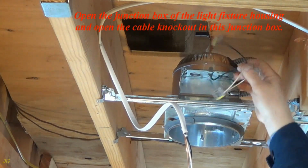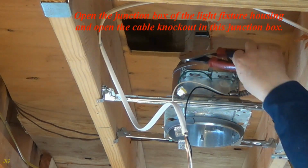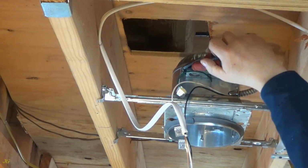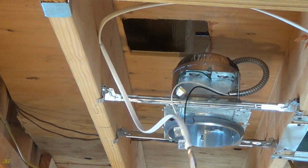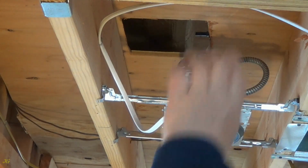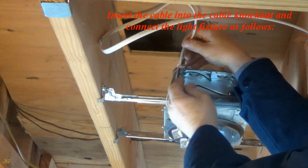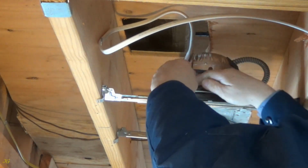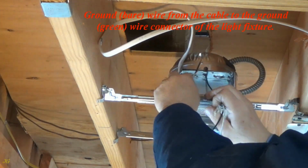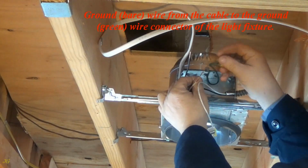Open the junction box of the light fixture housing and open the cable knockout in this junction box. Insert the cable into the cable knockout and connect the light fixture as follows. Ground, bare, wire from the cable to the ground, green wire connector of the light fixture.